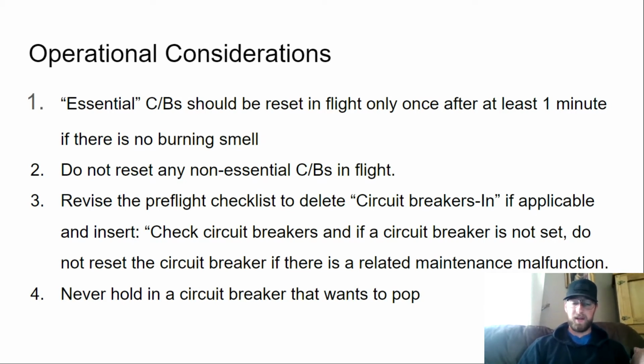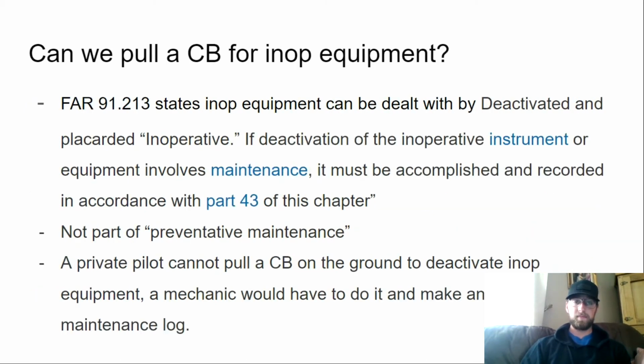And last one here, never hold a circuit breaker that wants to pop. So never keep that thing pressed in. This will allow the surge to pass on to the wiring and appliance down circuit of the breaker, leading to damage and even potentially a fire.